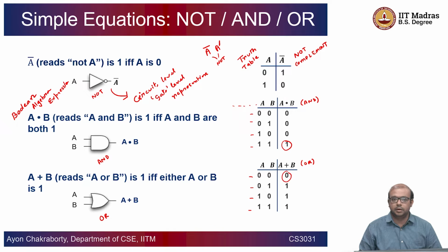These are immensely useful when we try to design circuits, particularly so when we try to simplify circuits. For example, given a Boolean expression that we have already studied or seen in the last class, it may have a circuit realization, but if you are able to simplify the Boolean expression using these theorems or axioms, you may be able to get a circuit realization that is way simpler, right? Which is going to save you the number of gates or the number of connections each gate can have, right? So you can do some kind of an optimization on the circuit design.